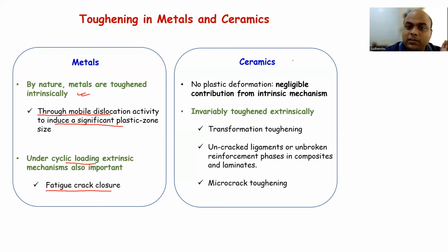Okay. On the other hand, ceramics have negligible plasticity, right? Very, very little plasticity. So there is a negligible contribution from intrinsic mechanisms. By nature, ceramics will show very small or no plastic deformation. So if you want to increase the toughness, it has to be predominantly extrinsic in nature, right?